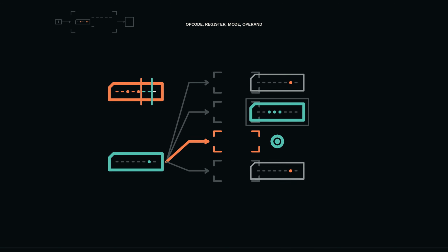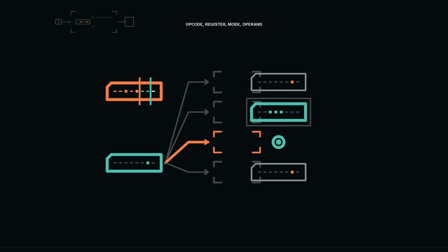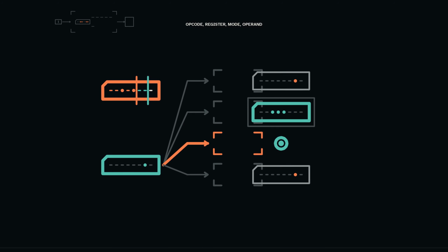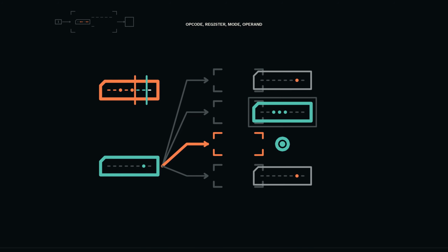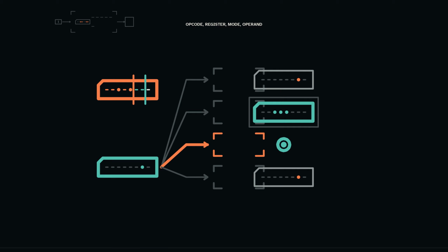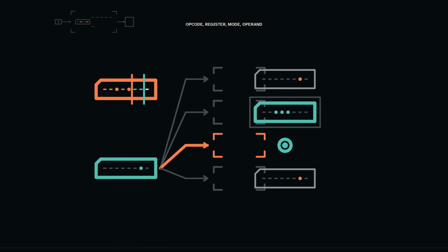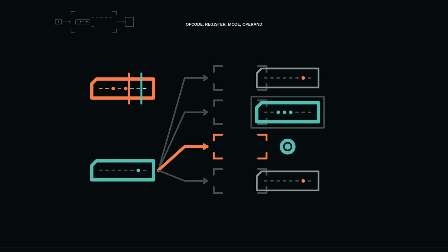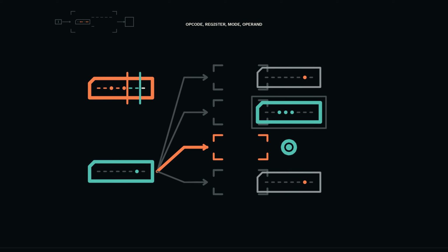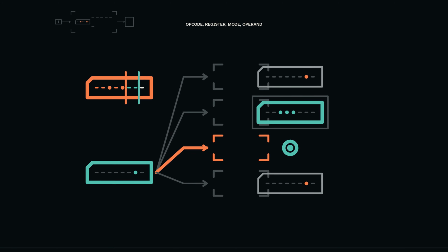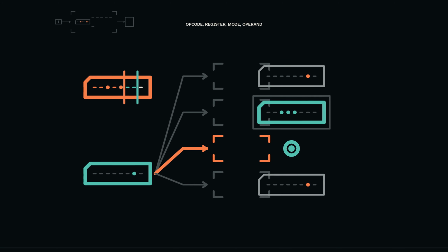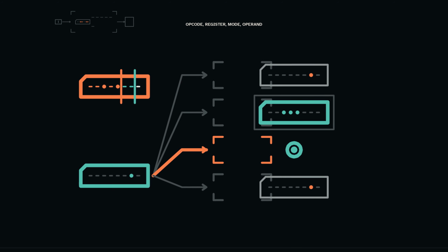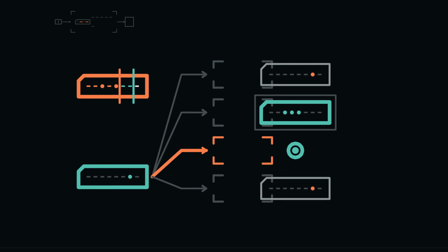For a register form binary operation, B does not use all 256 values. Its lowest 2 bits select R0 through R3, and its upper 6 bits must be 0. Consider bytes hexadecimal 28 and 02. Opcode 5 selects add, A selects R0, I is 0, and B selects R2. The instruction adds R2 into R0. If B were hexadecimal 82 instead, the low 2 bits would still name R2, but the reserved upper bits would be non-zero. SE8 faults rather than accepting a hidden alias. A strict contract makes malformed programs observable.